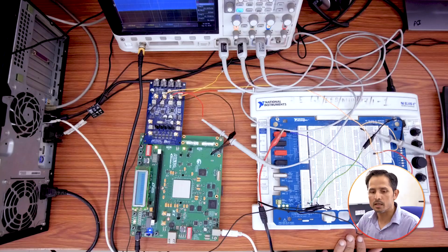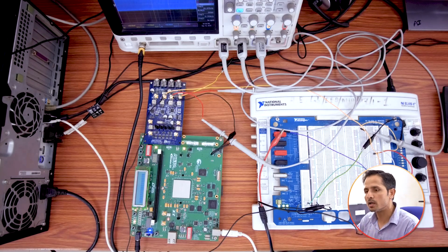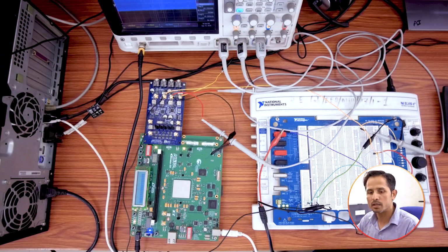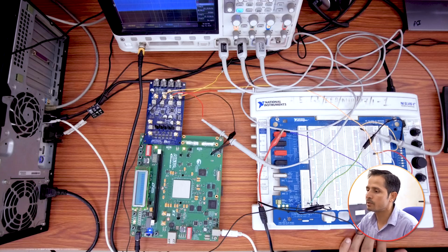So let me start by introducing you to the platform. First we have to install the Altera Complete Design Suite software. It will automatically install two basic tools: DSP Builder, which is used to design FPGA implementable programs, and the other one is the Quartus software. Quartus is a tool to synthesize these blocks, and they can be transferred into the FPGA boards. So let me start by first introducing you to the DSP Builder environment.